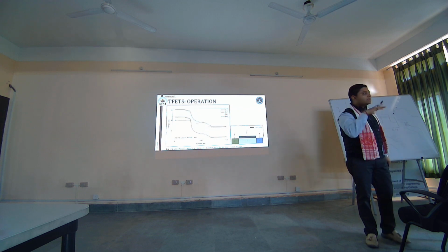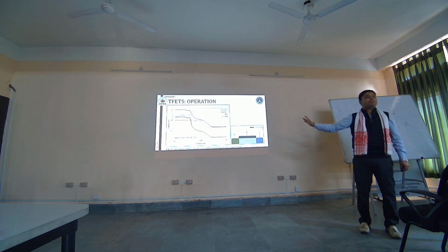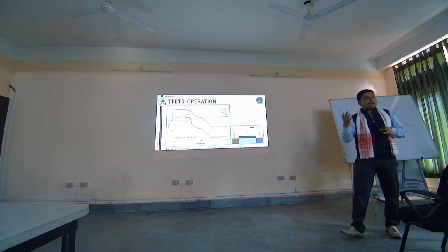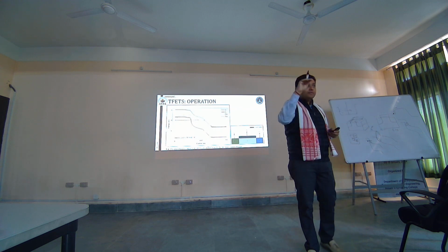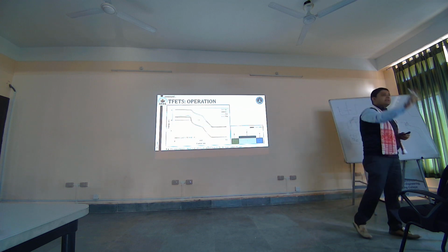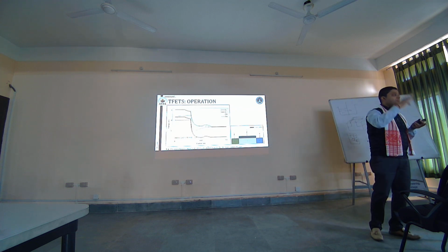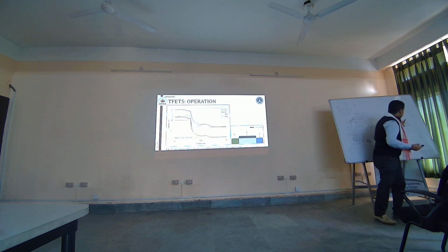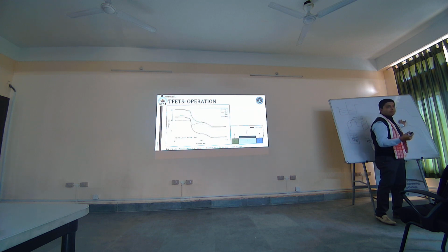If the thermal footprint is very small, it means it is going to have a very good subthreshold swing. Now what is subthreshold swing? It is the amount of voltage for which you can reduce 1 decade of current. So it tells about the switching performance of your device. Since this has these limitations on both sides, its subthreshold swing is very good. And subthreshold swing is a measure of low power applications of field effect transistors. Therefore these devices are now mostly explored. This is one of the reasons why they came to be more explored.